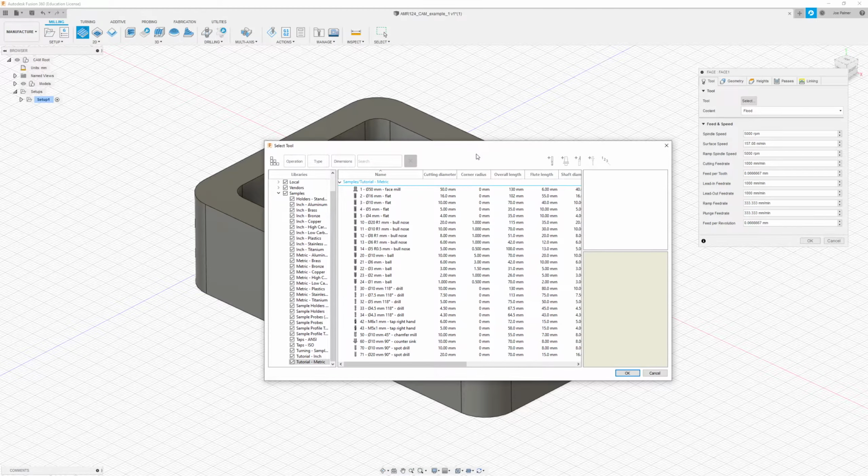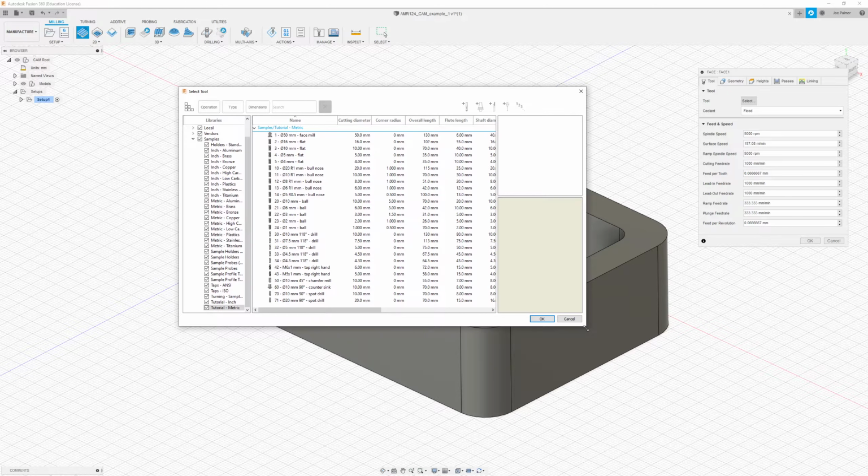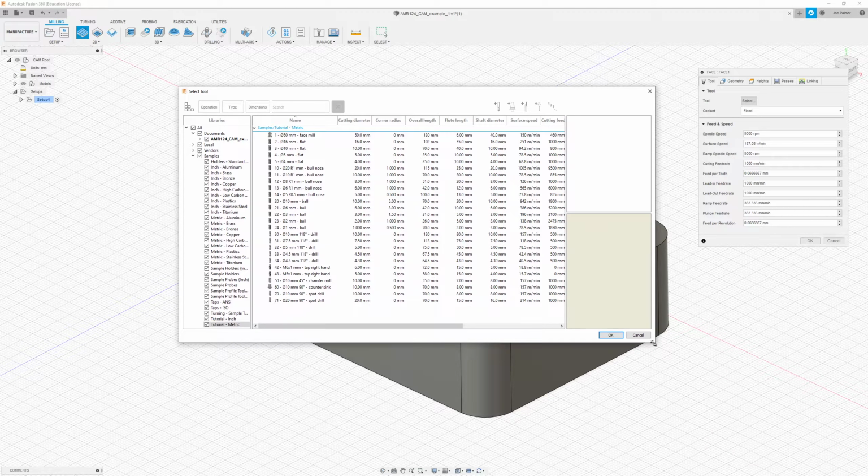What you'll often find in an industrial setting is that you have access to a limited number of tools and you need to design your components to be able to use those tools. If you are constantly designing components which need new tooling to be ordered, you're not going to be very popular in the workshop, and your components might not actually get made. So we're going to try and stick to using just the tools within this particular library.